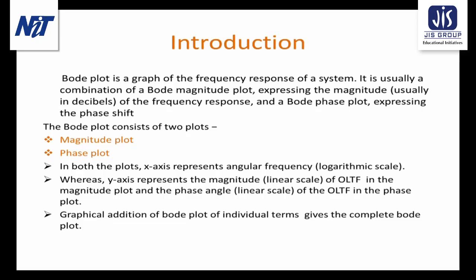So, Bode plot is the graph of a frequency response of a system. The magnitude and the phase of the frequency response against the frequency can be plotted directly on a linear scale. But the main disadvantage with the linear plot is cumbersome computations. So, to avoid this, it is convenient to plot the magnitude and the phase shift curves with a logarithmic scale.